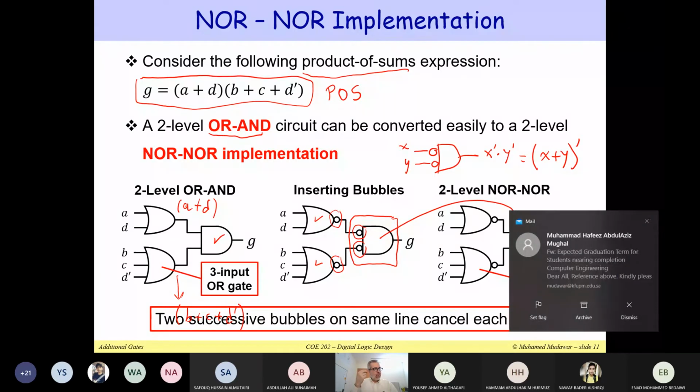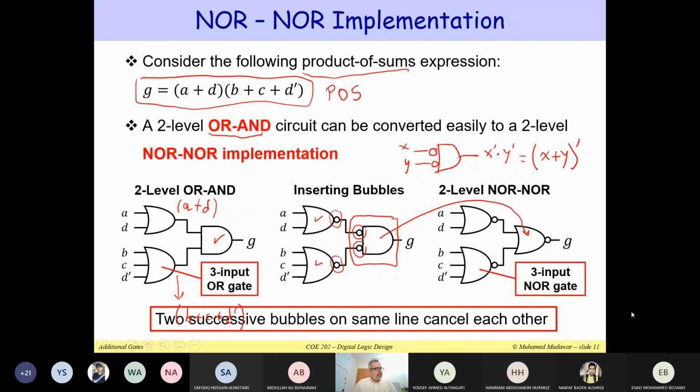So NAND is a gate, NOR is a gate, and these gates can be implemented very efficiently in CMOS. In fact, in order to implement, let us say, a two-input NAND gate, we only need 4 transistors in the CMOS technology. If I would like to implement AND, sometimes people use a NAND followed by an inverter to implement the AND.